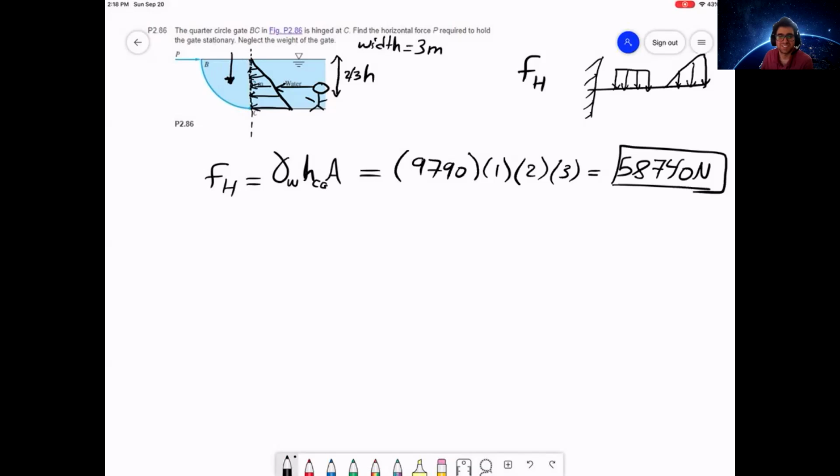It's just gravity, the weight of the water. Yeah, it's just the weight of the water on the gate, right? This curved surface has water filled in its cavity, so this weight of the water is pushing downward on the gate. That's why this vertical component is there.